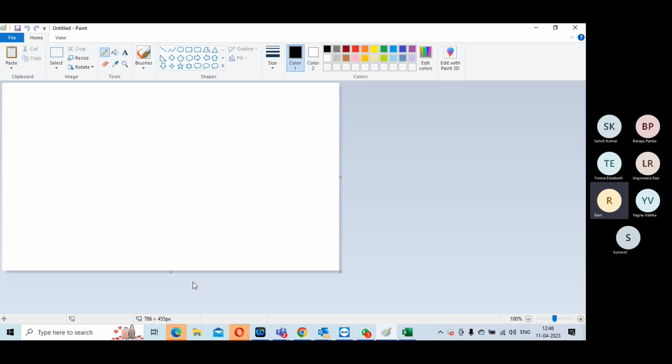All the power domain stuff should be taken care of. But congestion means we can't estimate congestion or timing just from macro placement where the floor plan is done, right? Floor plan is a loop until CTS. Until routing also you will look at whether it is routable, and before you freeze there are iterations. But the point is, when you say this floor plan is good, this is what it means. Okay, so module placement.